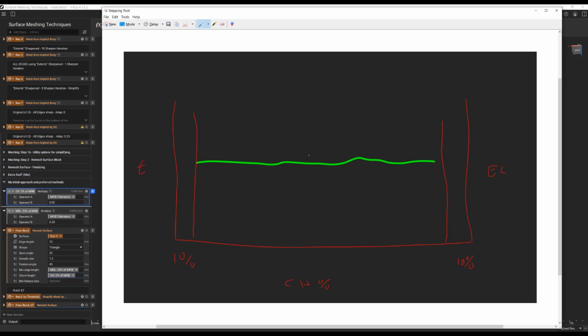the block took the most time to solve, and the overall time plot kind of looked like that, with a sweet spot being from about 2 to 4% of the mesh from implicit body tolerance input. So that's more or less the reason why I start at 2%. It gives me the most fidelity with the least amount of time.